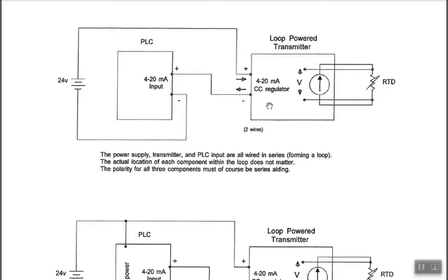And it's a pretty cool trick. I mean, there is a microprocessor inside here that does need power, and it's going to steal its power from the 4 to 20 milliamp loop, which means if that current is as low as 4 milliamps, the circuitry in here has to run on that. That's all it's going to get.